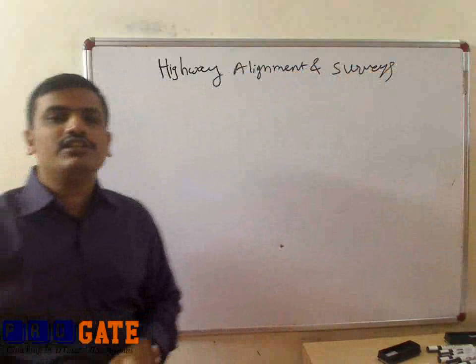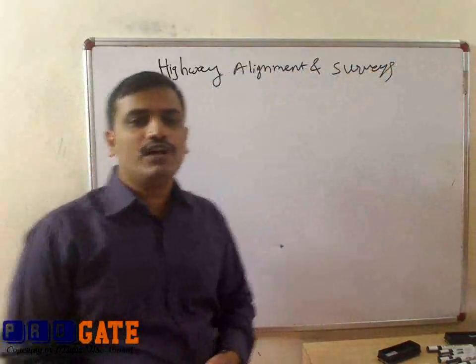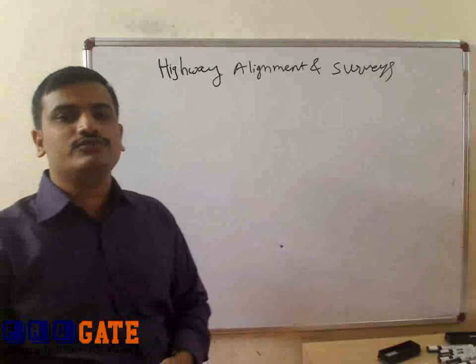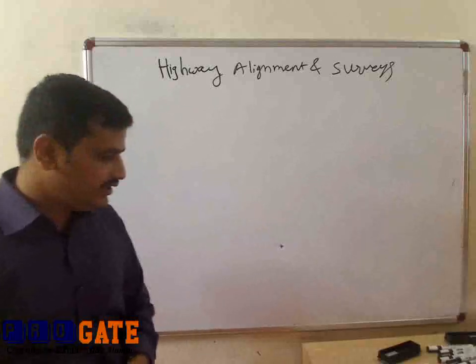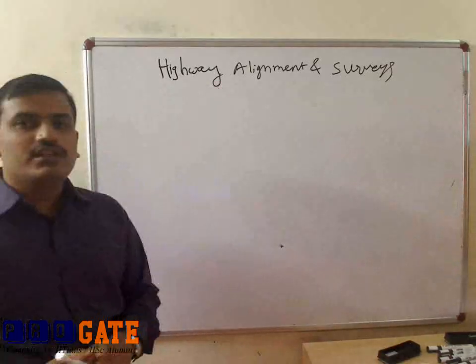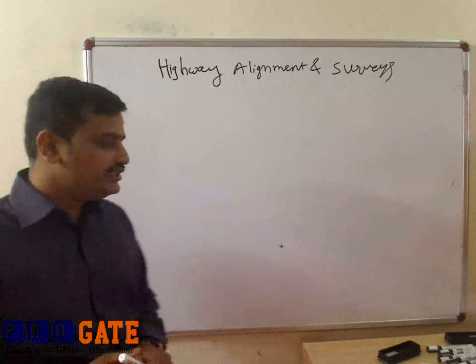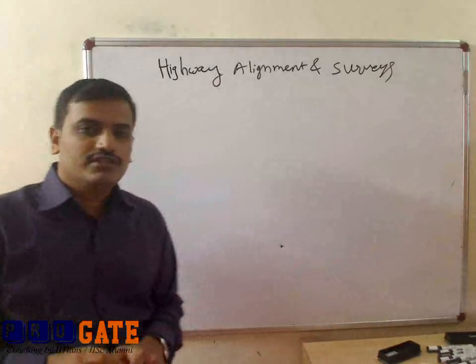After going through the initial highway development programs of India, we will have a look at how highway alignment and surveys are chosen for a particular highway project. Whenever we choose the highway alignment, it should be short, easy, safe and economical.